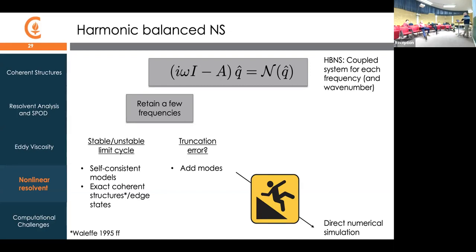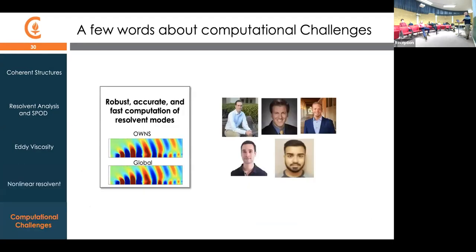The point that I'm wanting to make here is that there are probably happy in-betweens, and there are probably very interesting and useful turbulence modeling approaches in this frequency domain. The hope is that with the simple transition scenario I showed, we could get by with just a few modes. If you can do twice that many modes, you can get much richer structures and so on. So my interest here wouldn't necessarily be in a paradigm shift away from time domain calculations, but more on the modeling side. Still, there are issues that have to be confronted.